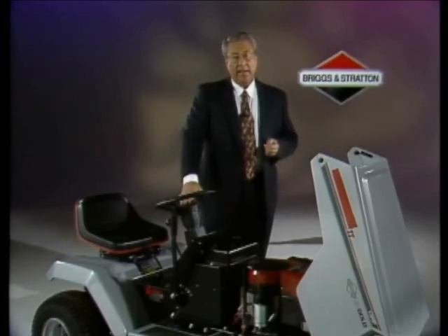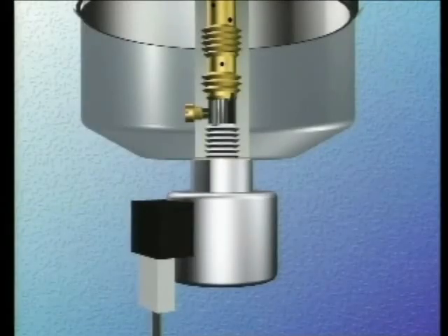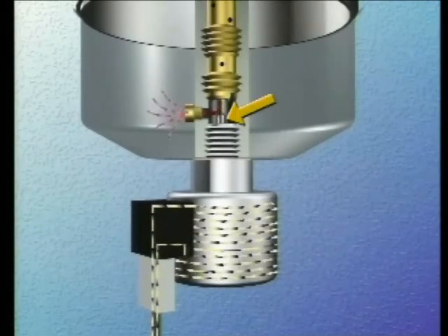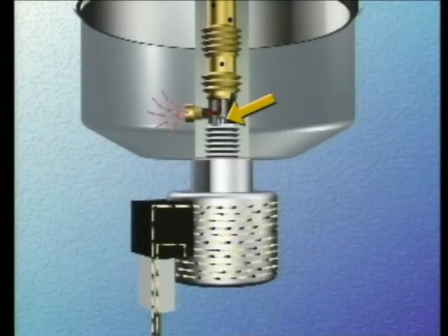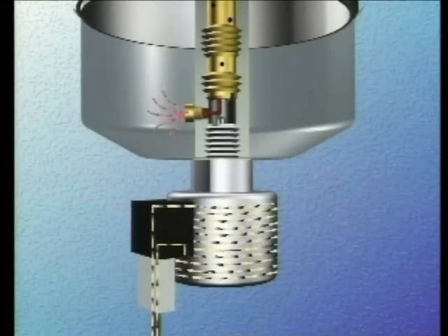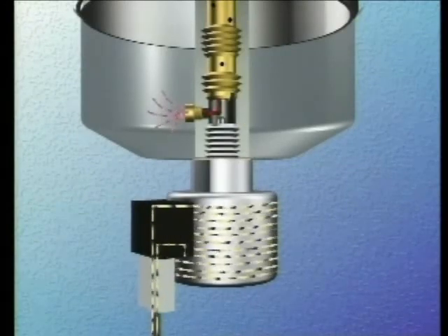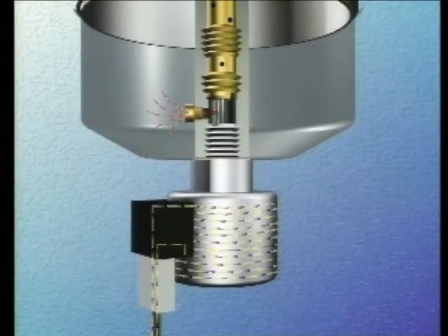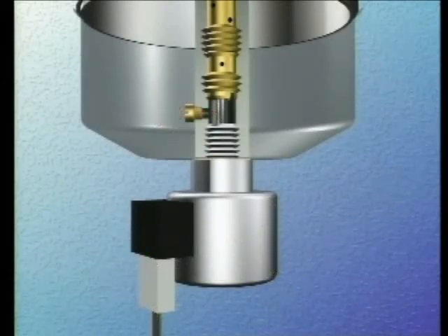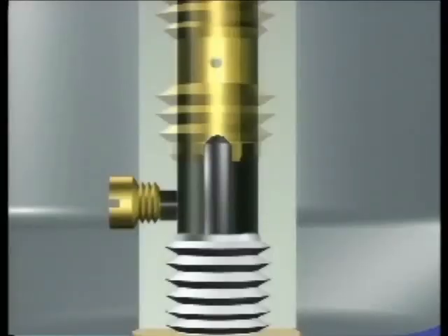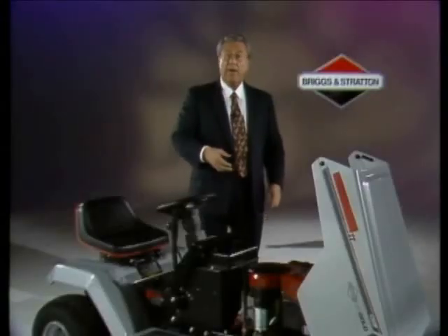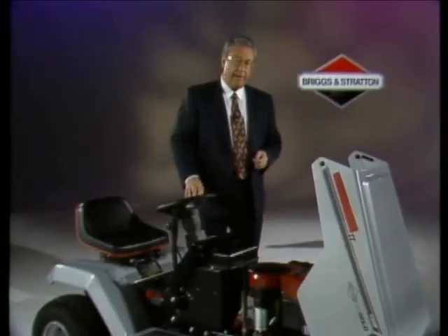To prevent this from happening, anti-afterfire solenoids have been developed. They work almost like an electrically controlled plug. When the ignition switch is in the on, run, or start position, battery current is applied to the solenoid. This causes a spring-loaded plunger to retract into the solenoid's body. When the engine ignition is turned to the off position, the current to the solenoid is cut, and the plunger returns to its relaxed, extended position. This forces the plunger into the emulsion tube and prevents any more fuel flow to the engine. With the fuel flow cut off immediately, there's little chance of afterfire.